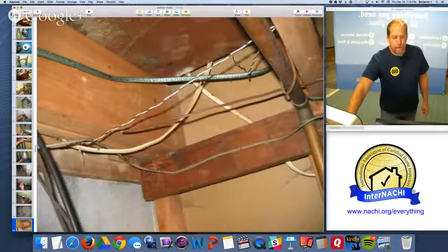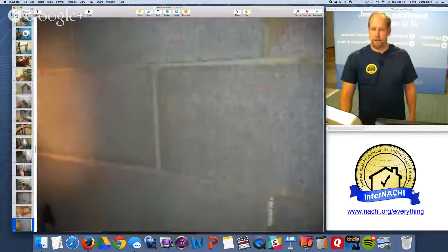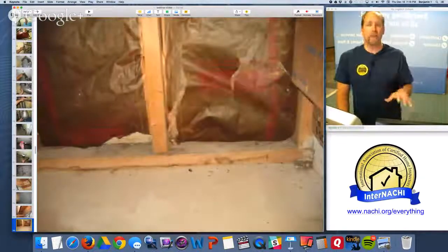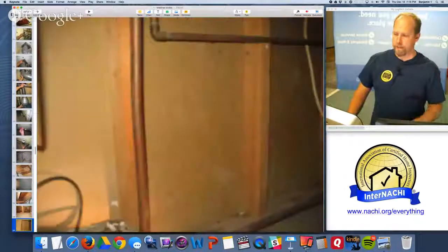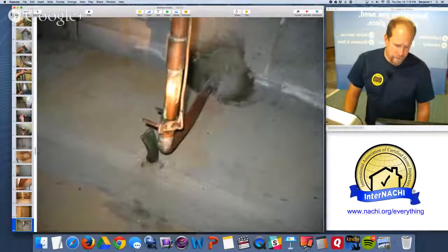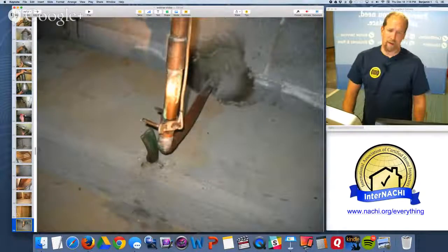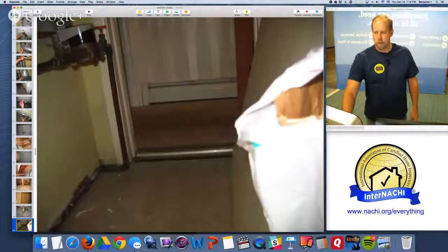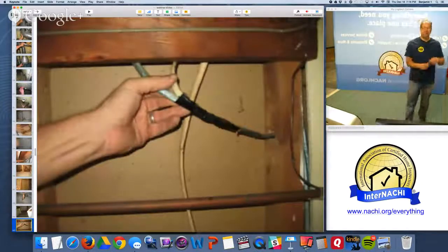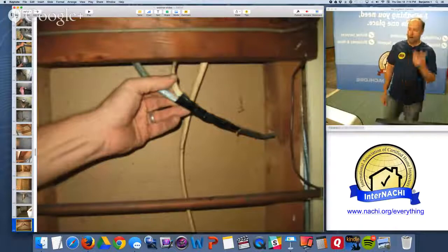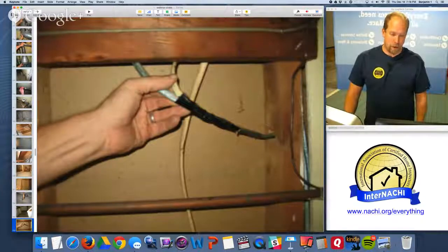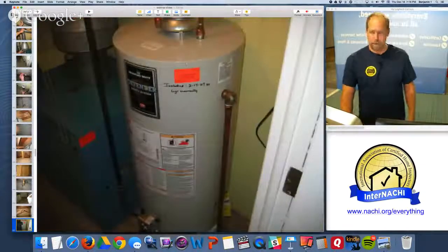And now I'm looking at structure as well. Concrete block, little crawl space area, not very big. I'm looking at wood, untreated wood in contact with concrete, and we have water problems down in the basement. A main water line was cut off and a new water line was installed. Improper electrical junction. They just spliced right into an existing cloth Romex, and so they didn't use a junction box. They didn't do electrical wiring in this house very well.